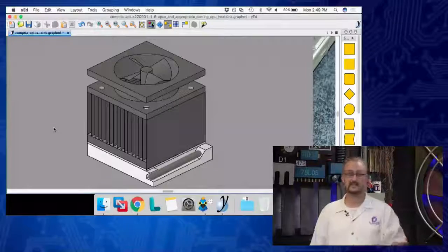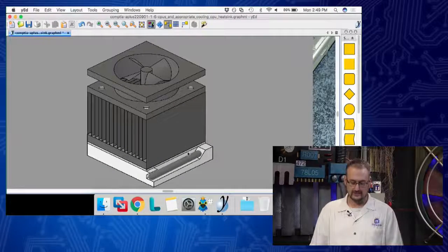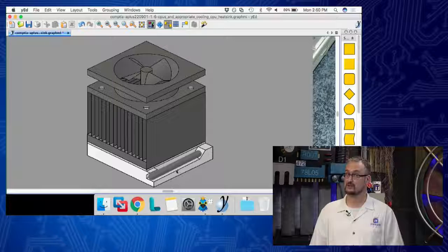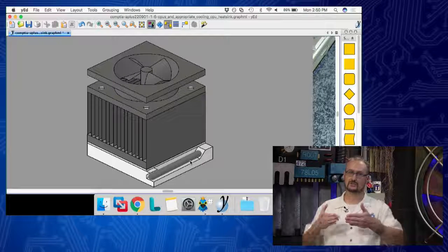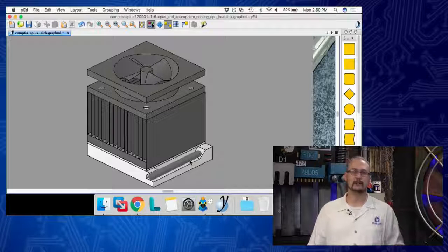So that being said, let's go ahead and talk about, when it comes to the CPU itself, one of our first primary components in this overall cooling system. And that's something known as a heat sink. All right, and I've got a little bit of a diagram here, and we'll actually look at a heat sink too coming up. I can almost guarantee you this is a diagram of some AMD socket because of that zero insertion force socket that we talked about. The little handle we showed you on the motherboard, when I open it up, kind of pulls the socket back and releases those pins that it's grabbing onto.